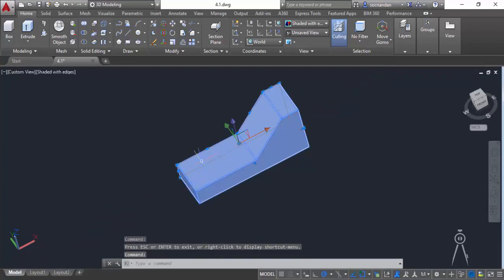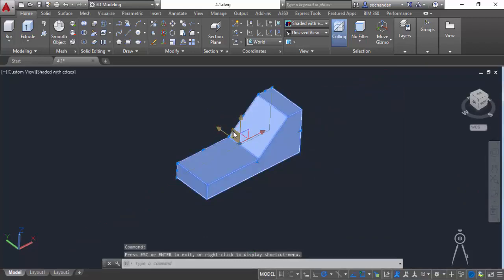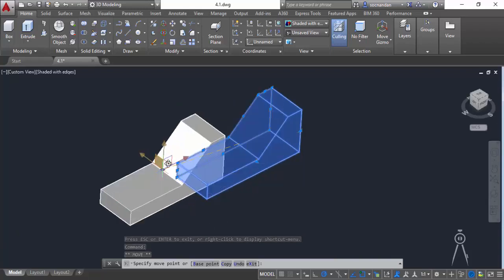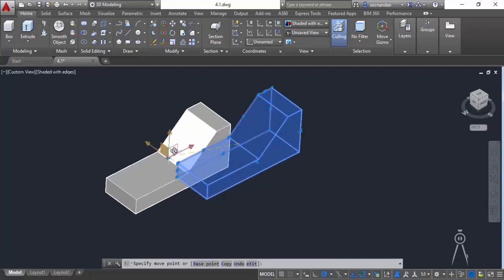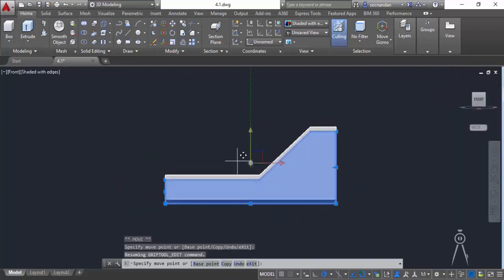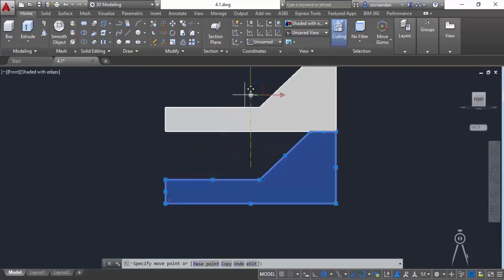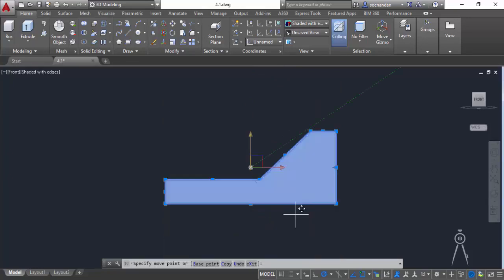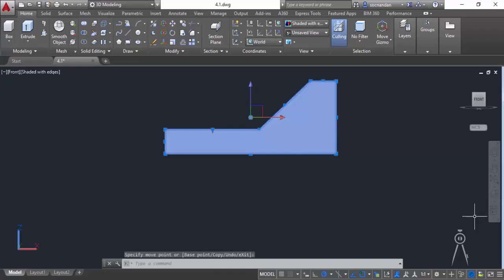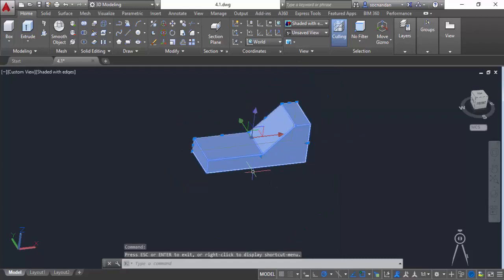Let's say that we want to move it on some other plane. For that, let's orbit this again and select any other plane. So in this case, I'm selecting this plane. And now even if it looks like I'm moving this object towards left, the object is still in movement in the selected plane, and that can be seen more clearly in this way. So even if I try to move my cursor towards left, I'm not able to do so. I'm only able to move it in the upward and downward direction, and in this way you can restrict its motion in any single plane. Now let's turn it back to this position and let's try other gizmos which we have.